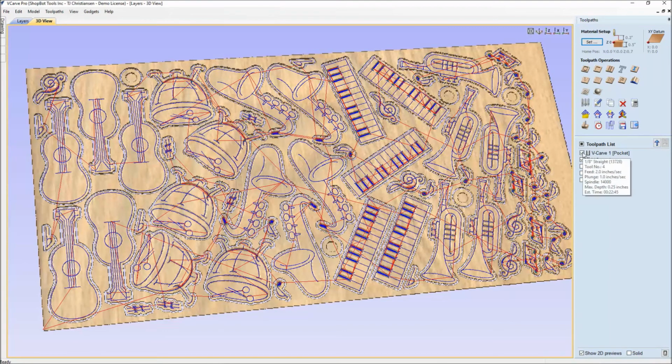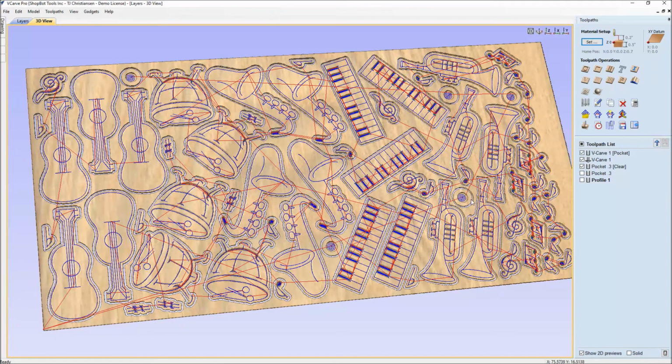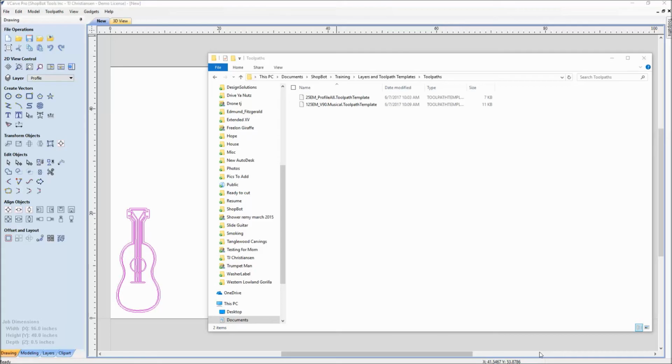The next one here I have is the clearance, which is just the 0.3 for that pocket. And then again, you'd go through and set these all up for your pockets, for your profiles, and work your way down through. So I went through and finished these, and you can see here is the end mill with the V carve for doing our V carve, and then the profile with the 1/4 inch bit for doing around all of our parts.